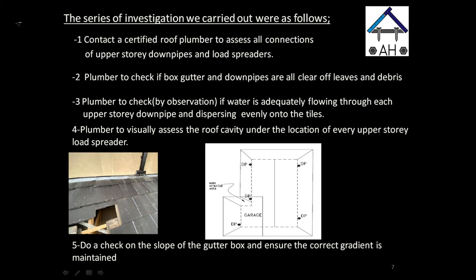For a 125 by 165 deep box gutter, and then we had as well 5 downpipes that we particularly looked for, we needed a minimum gradient of at least 1 to 500 as per the Australian standards. Of course, we have to do a specific design for that, but if we can get between 1 to 250 or 1 to 500, then it is pretty reasonable value to work with.